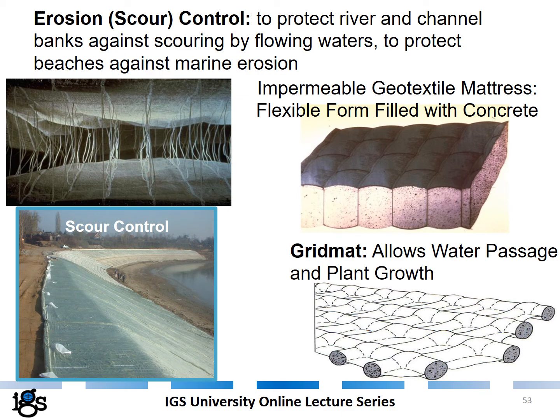So when you pump in concrete, it basically works as a flexible form, and the inside gets filled with concrete, as seen here. So you produce a liner, and the beauty of it is you can do this even under the water. Just spread the mat and start filling the concrete, and it settles to the base of the canal or beach, and you can easily form the concrete liner. Here is a picture where this concrete liner has been completed.